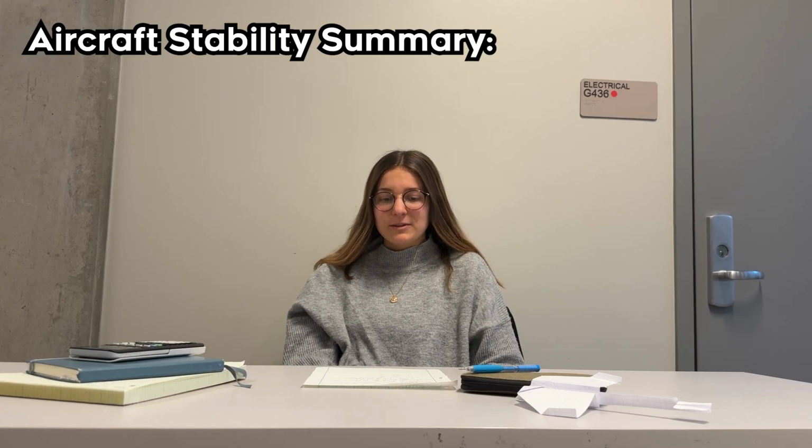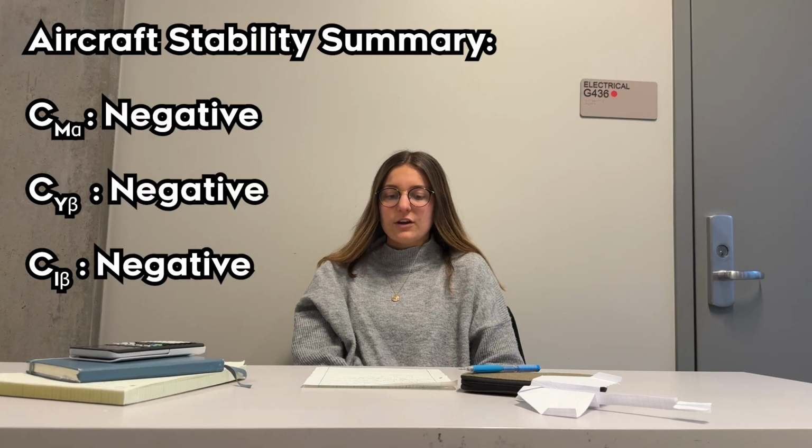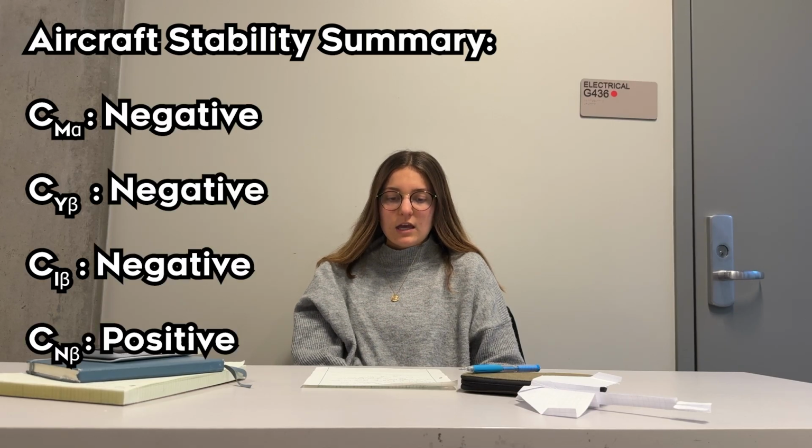And how we determined this was our CM alpha, CY beta, and CL beta were all negative, and our CN beta was positive. These control derivatives are essential in determining whether or not our aircraft is stable or unstable, and of course we want a stable aircraft. And so we were looking to get these control derivatives and also a static margin between 0 and 10%, and we got that. And so I would say that this project was very successful.